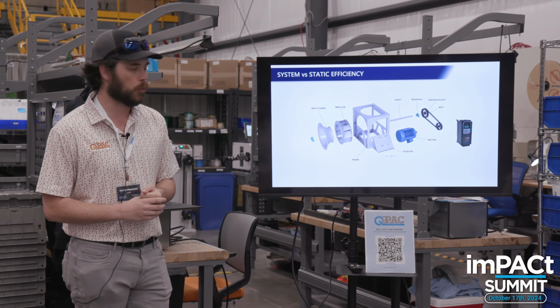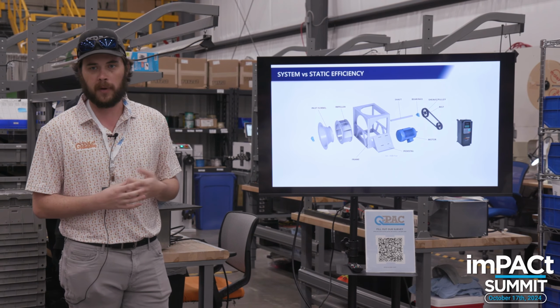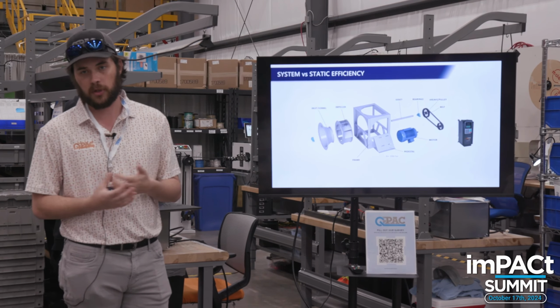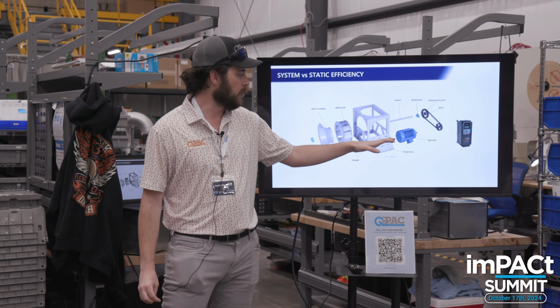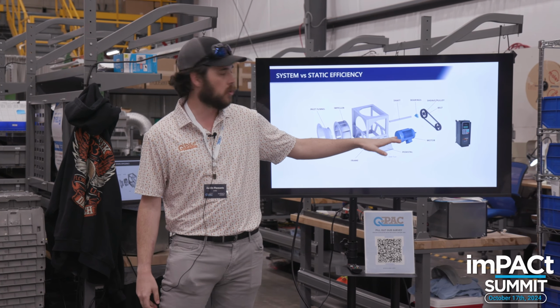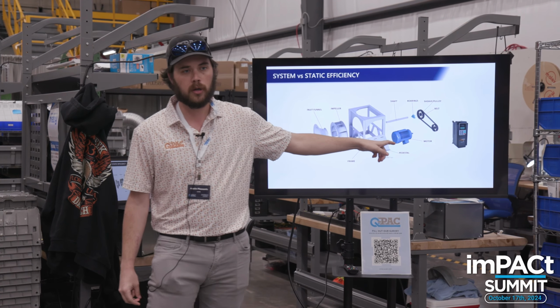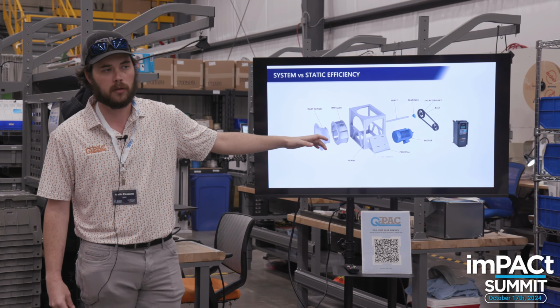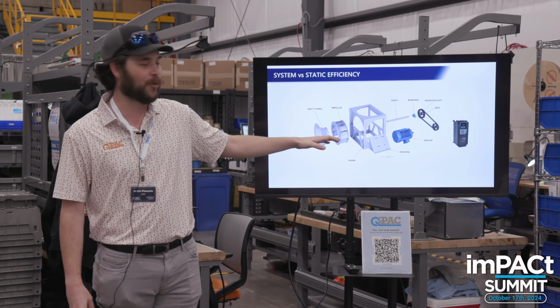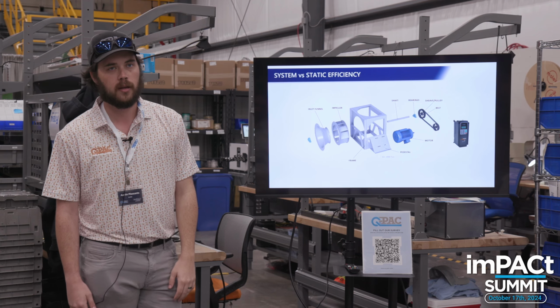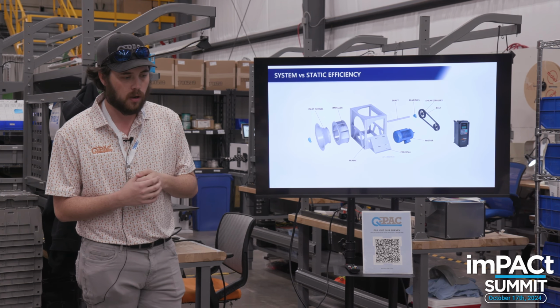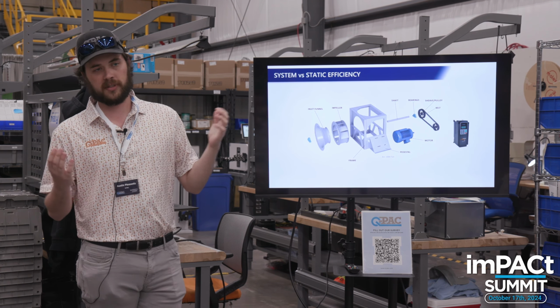So if you have an old rusty shaft and a rusty, falling apart bearing, your efficiency obviously is not going to be as good as a brand new bearing, right? So sometimes when people look at an old system, they look at the old spec sheet for the motor, find a data sheet somewhere that's probably hand drawn maybe. Sometimes these things are so old, but they see a motor efficiency and they say, okay, the existing motor is 55% efficient, for example, right?